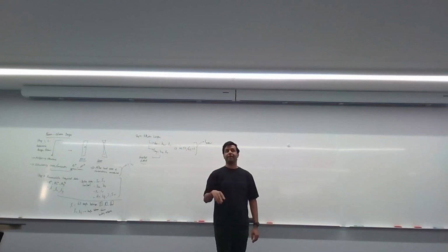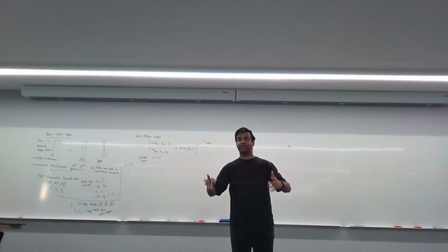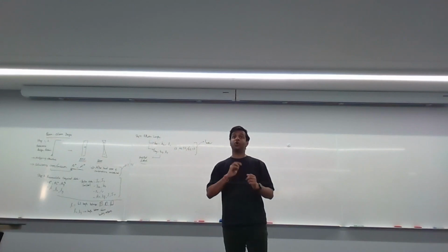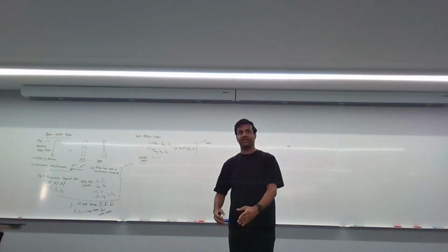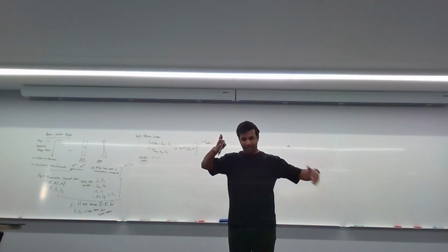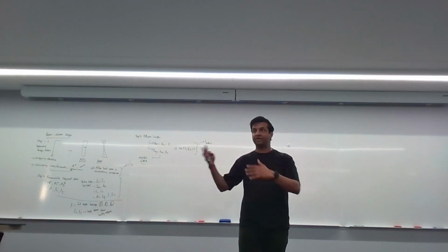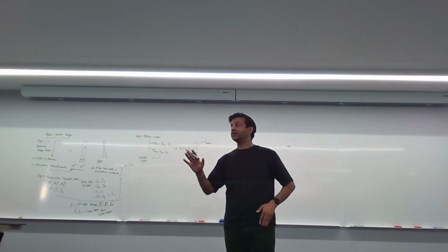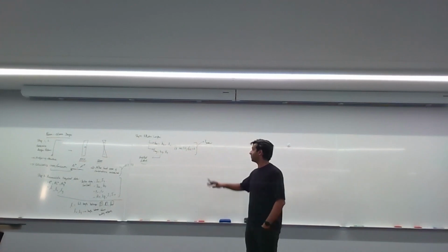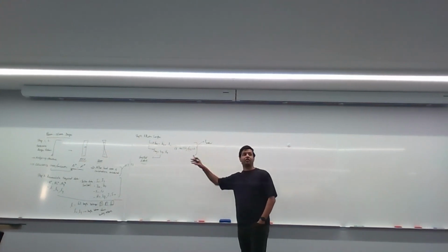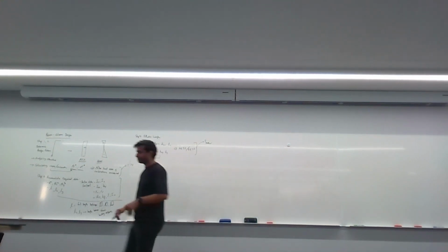But most of the time in a beam column question, they've drawn out the entire frame for you in 3D. If you know exactly what the frame looks like, that means I know that this column which I'm designing has a beam coming in this way, a beam coming in this way, and I know what the sizes of these beams are, etc. You cannot use the idealized method anymore. You have to use the gamma method. The gamma method is a lot more accurate in calculating the effective lengths. Remember, all of this is just for step 4, effective length.